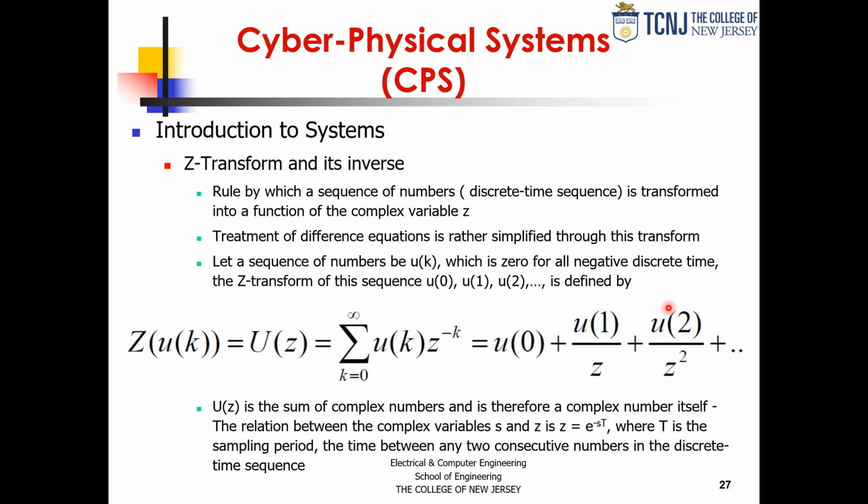In fact, in digital systems that do digital signal processing, a Z to the minus one operator is considered a register. It does the same thing as a register. It's a time delay of one sample or one clock cycle. So I'm trying to relate these things that you have seen before, mathematical ideas, to hardware that we're going to be talking about as soon as the next chapter.